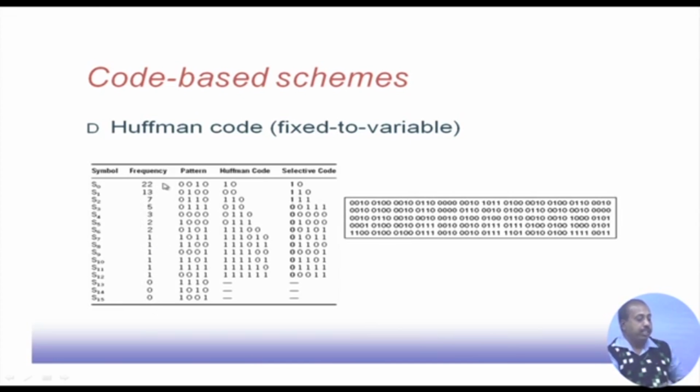In a fixed dictionary structure, a fixed to fixed length coding, what we would have done is store all these patterns S0 to S12 in the dictionary, and for decoding we would just send the index of the dictionary. But since there are 12 entries, for every slice I need to send a 4-bit address.